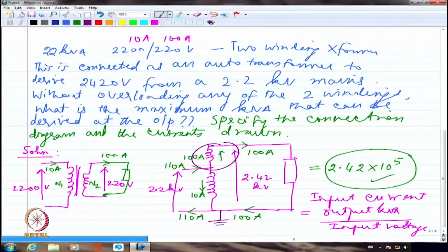The bus is a bus bar or a junction point. From the junction point, you probably derive so many load connections. So we call this the infinite bus because we assume that its capacity is infinitely large, which is not really true, clearly. But compared to 210 gigawatt, which is the overall generation capacity of our grid, 1 megawatt is less than a drop. No problem, right?